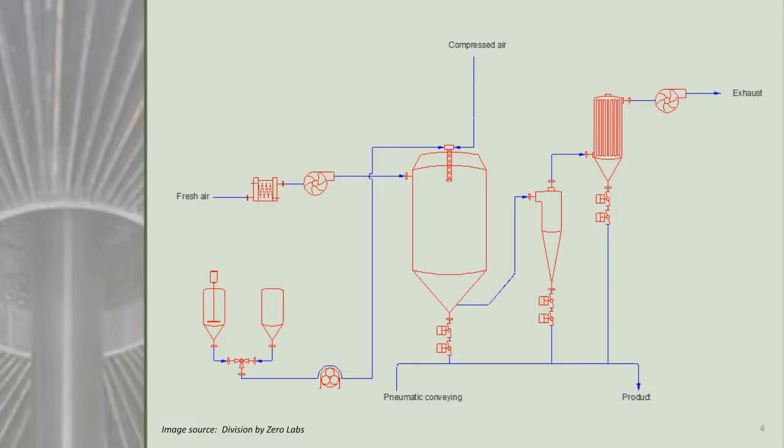Here's just a basic process flow diagram. This is a short form tower spray dryer and shows the basic components. Hoping you can see my mouse cursor, but basically we have a tower, and in the top I've depicted a two fluid atomizing nozzle. So compressed air is used as the energy source to atomize this liquid. The liquids start in these feed tanks and they're pumped up to the atomizer, where they're impinged violently by this compressed air. That's what causes the atomization.